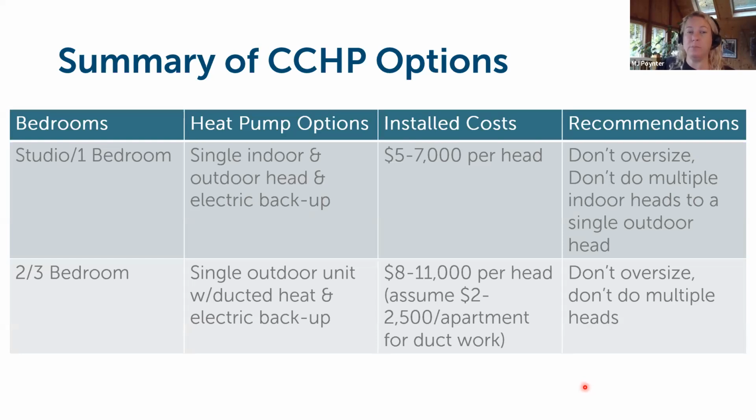If you have an existing building and you're adding heat pumps, and you already have a backup heating system, it's usually more cost effective to stick with that backup heating system and potentially undersize your heat pumps so that you don't have the short cycling and that they're operating at their best possible during the majority of the heating season.